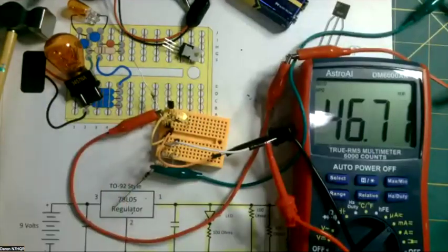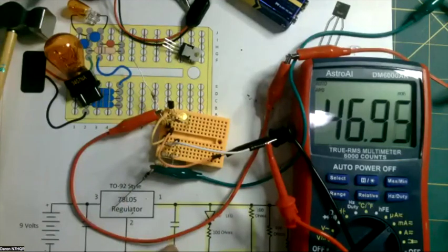What voltage are you at now, Aaron? I'm at 15. The current's dropping off. Yeah, I'm wondering if that's just starting to fail in the regulator. Can you measure the voltage and see if it's folded back? Well, the LED's still on, so I'm going to guess it hasn't.